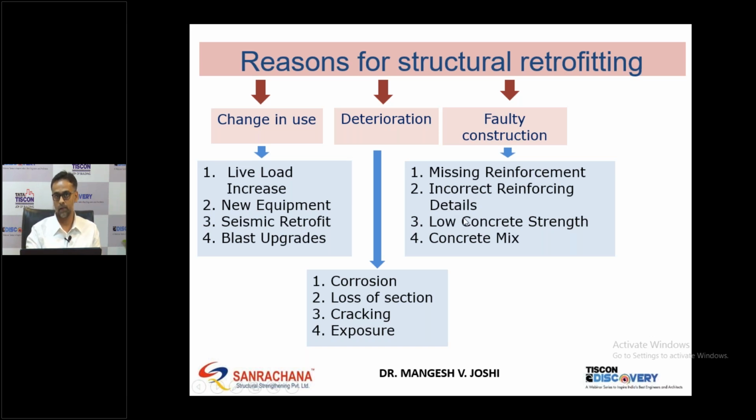Low concrete strength. Now we are in the age where we are recommending really high grades of concrete, M60, M70, and beyond, and producing that consistently is a challenge. It's not easy to produce that type of concrete quality consistently, and in the process if we fail, we come to know after 28 days. So many a time it's not possible to demolish it, so we have to offer some solution to retrofit the structure.